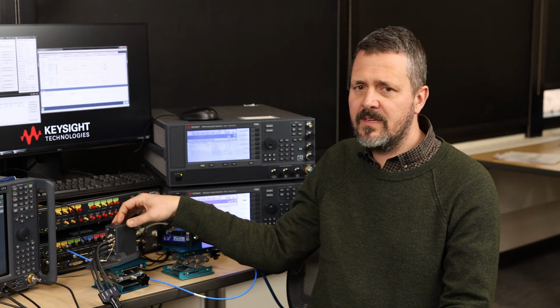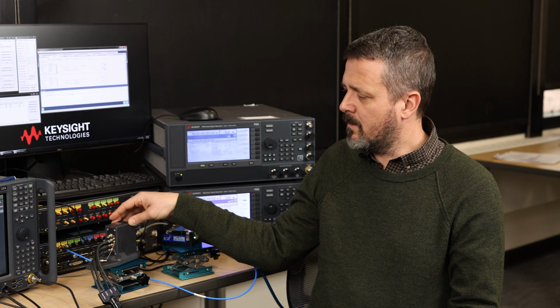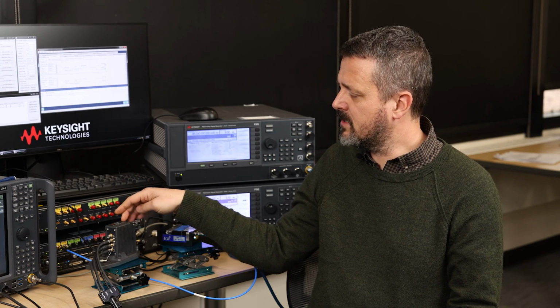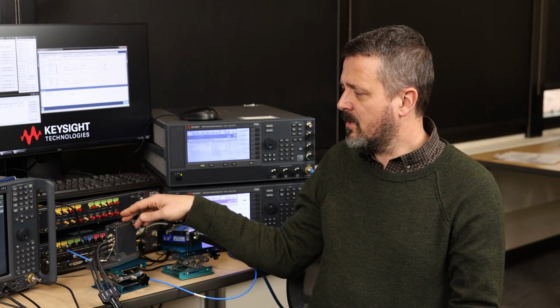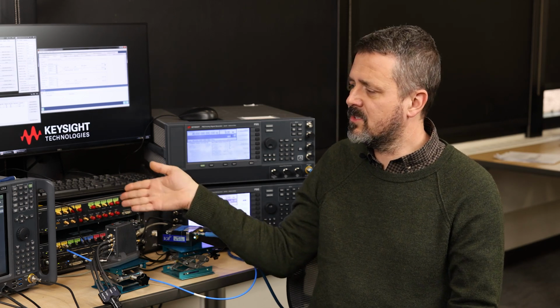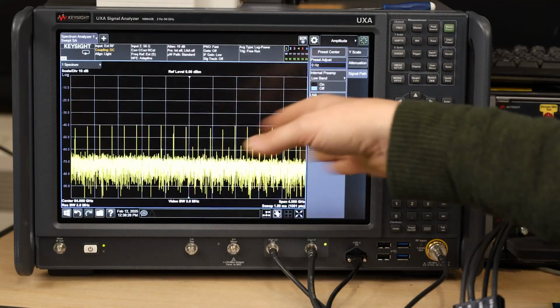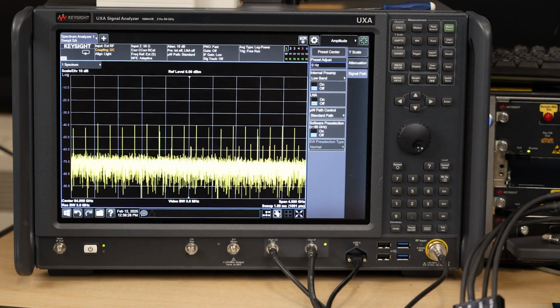The V3050A has a bank of filters, which are pretty good as our preselector. It also has software preselection above 90 gigahertz. Software preselection is turned on by default. For this case, I don't need software preselection. So you can see my signal is pulsing.